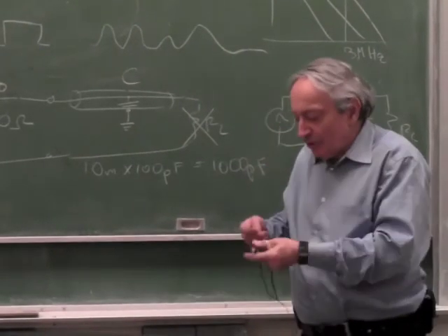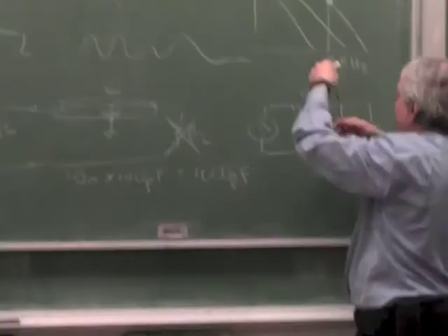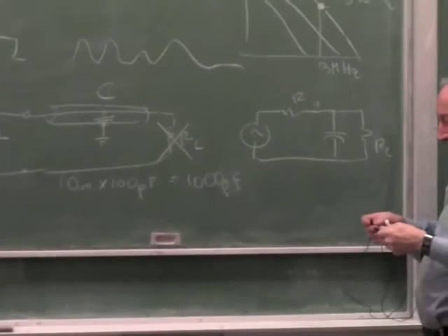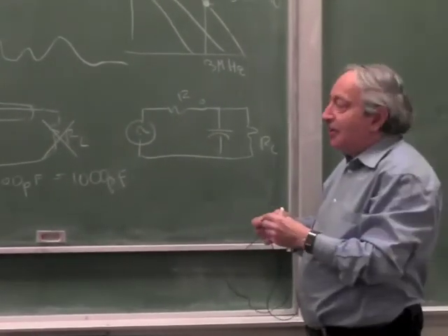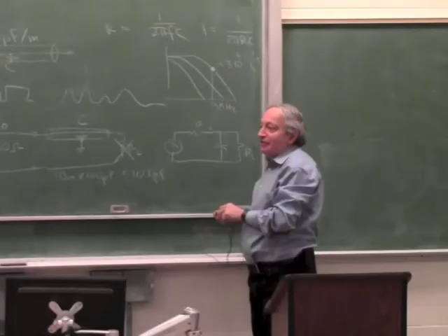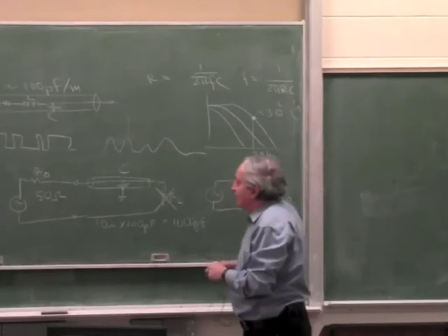So whenever you put a piece of cable, you calculate this number. If this number is high enough compared to your frequencies, you don't need a coax. But if this number starts getting close to a few harmonics above your frequency of interest, you have to switch to that. You have to use coax.